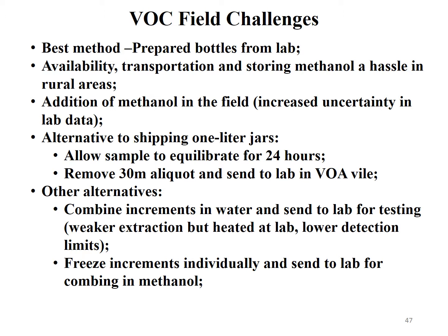So there are alternates to consider if the methanol method in the field presents problems, and Hawaii is perhaps unique in that we work on all these different islands, and there are shipping regulations because methanol is a hazardous material that limits shipping certain amounts of methanol by air from island to island. So consequently, due to those shipping restrictions, some consultants have had to resort to collecting individual subsample cores from the subsurface in vapor sealed small sampling tubes like an Encore tube, 5 to 10 grams, and shipping these multiple cores all frozen to the lab. The lab would then thaw them out and combine them in methanol in the lab.